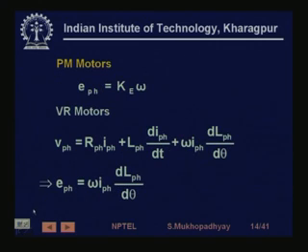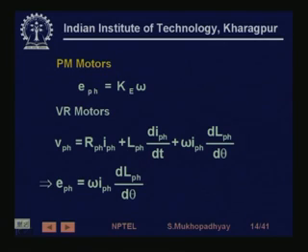If you see the equations, if the motor is rotating continuously, then the phase back EMF induced is proportional to omega, because the flux, it is a motor. So, when it is crossing the coil, the flux is getting linked. So, it is Ke into omega.